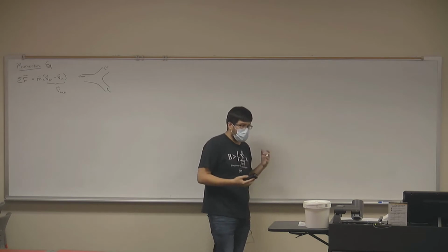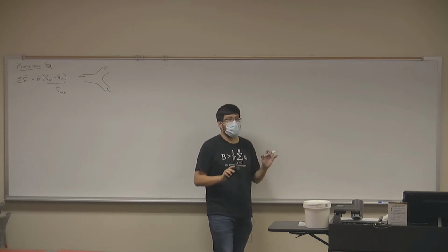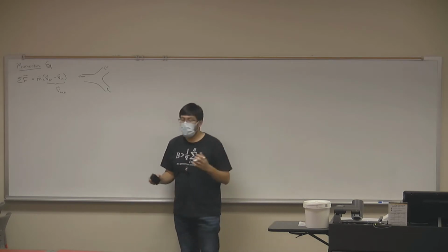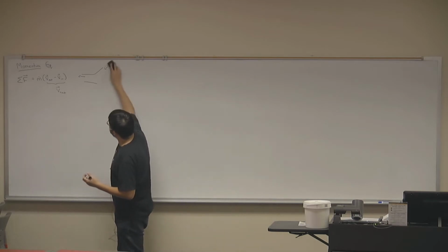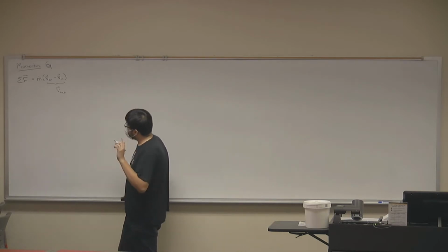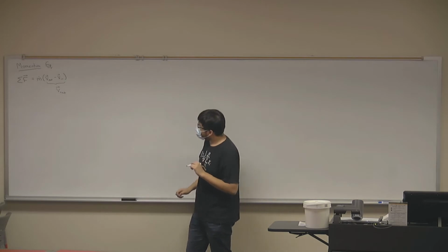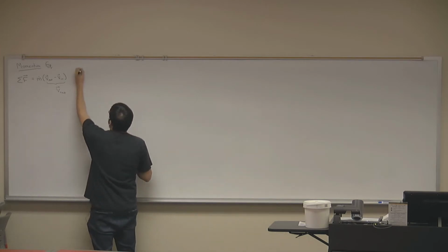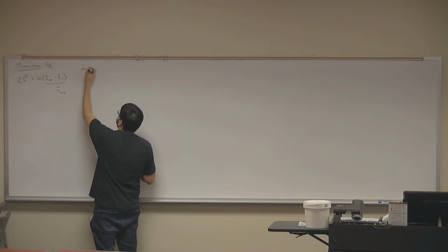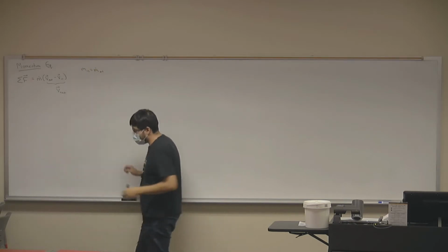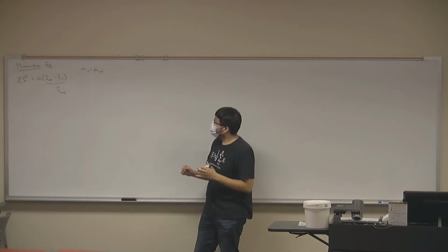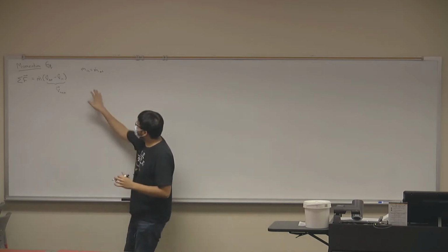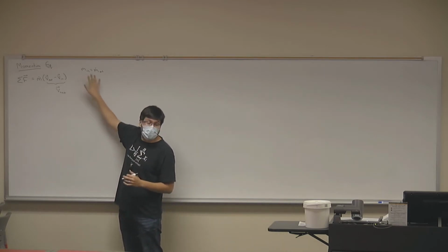Today I would like to work on an exercise where we have more than one inlet or outlet so that we can get used to this scenario. The second thing is, from the continuity equation, which we talked about on Monday, we got that mass flux in equals mass flux out for steady uniform flow in a non-deforming control volume. But again, we may have multiple mass flux ins and multiple mass flux outs.